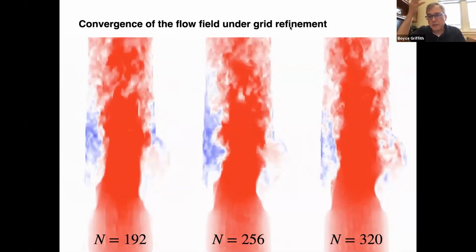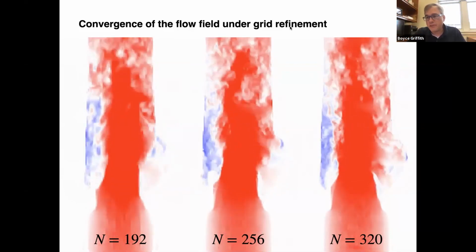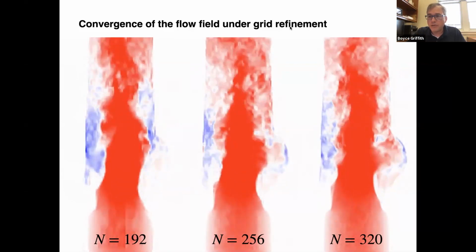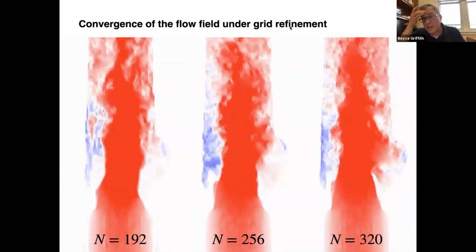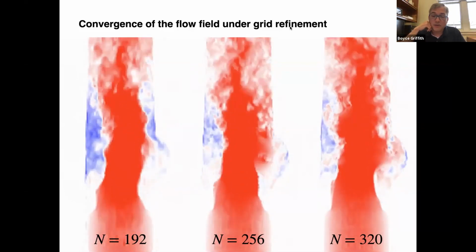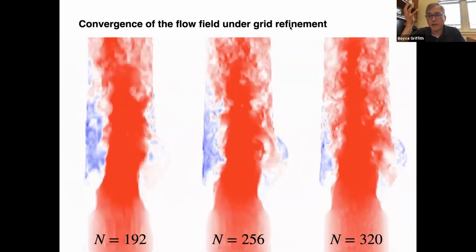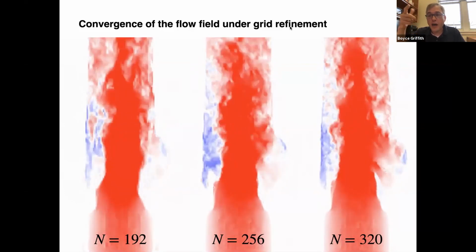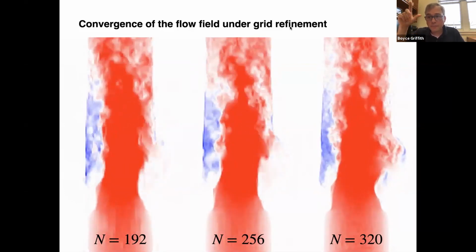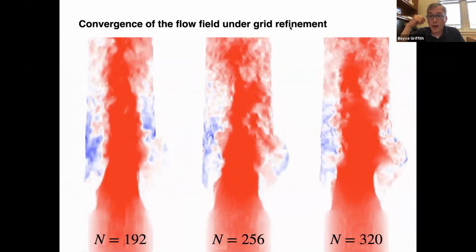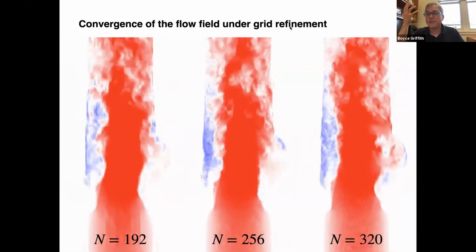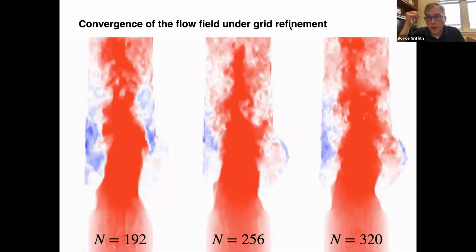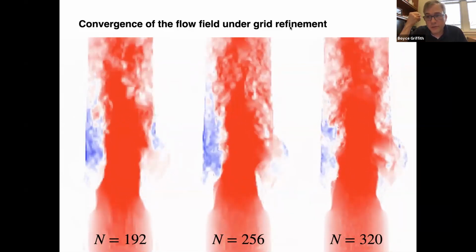If you've got a stiff material or penalty forces, that can really result in tiny time step sizes. We've been working for a long time to come up with efficient implicit formulations, and the numerical linear algebra for solving the coupled system implicitly is challenging. We have methods that allow us to take big time step sizes, but the solvers are expensive enough that it's cheaper to just do things explicitly.